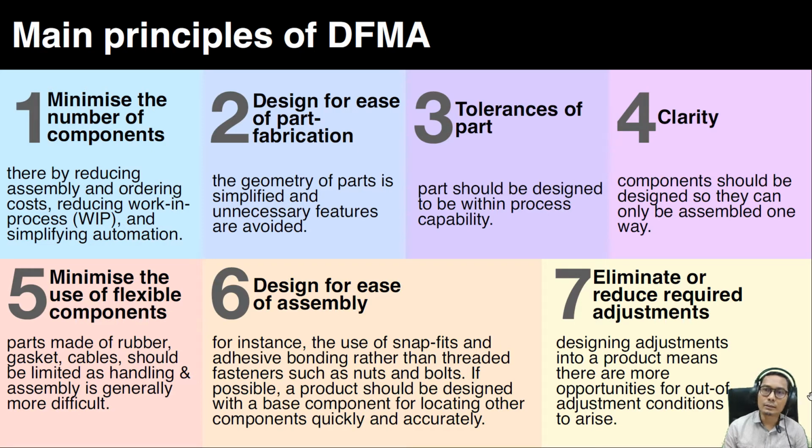And then the fourth principle is clarity. Clarity means that the components should be designed so they can only be assembled one way, which by using this principle, will ease the assembly process.